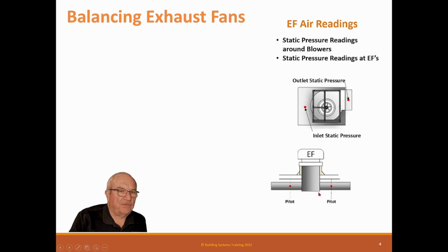So for exhaust fan readings, normally you can't get to this part right here to take a pitot to tell flow, and you can't just total the grills here if you have to, but you can also pitot the ducts as they come out. You may have to do two or three pitots and add them together. Of course, the static pressure is in this inlet plenum, and the outlet is 0.